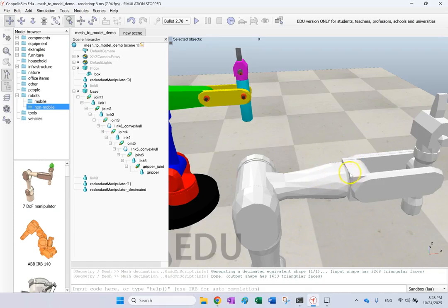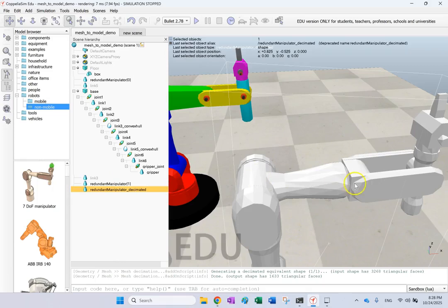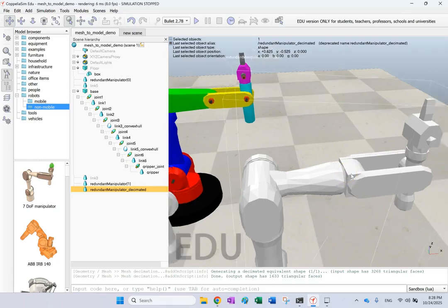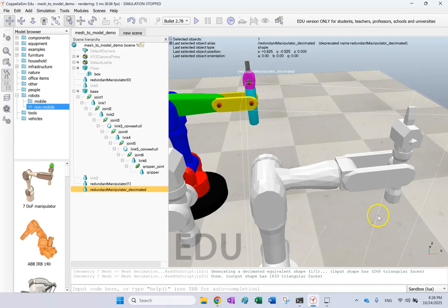If you want, you can do some local mesh edit, and instead of this non-convex shape, you can make it a convex shape if you want. Okay? So right now it's all one single mesh. But next I'm going to show you how to break it into individual mesh components that are connected together, and then you can merge them back again and make a convex hull. But you see here, this portion of the geometry, this cut here, doesn't play any role. So you can make it much simpler.